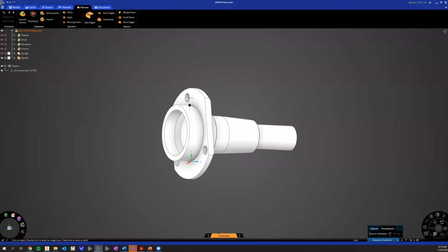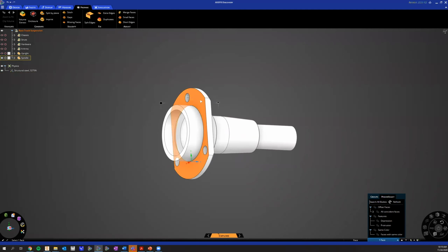The first thing I need to do is add a boundary condition where I want to fix this surface. Once again, I'm going to use the halo, a very convenient feature. And I'm going to head back. Now, instead of using the modeling tools, I'm going to click on the structure side, where I have access to different types of boundary conditions: displacements, forces, supports, and loads, different bearing loads. For this one I'm going to use a support, and I'm going to fix the surface here.